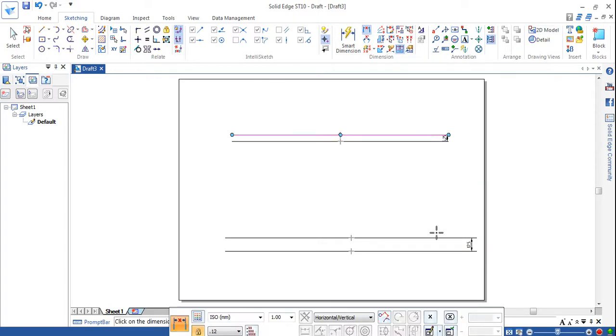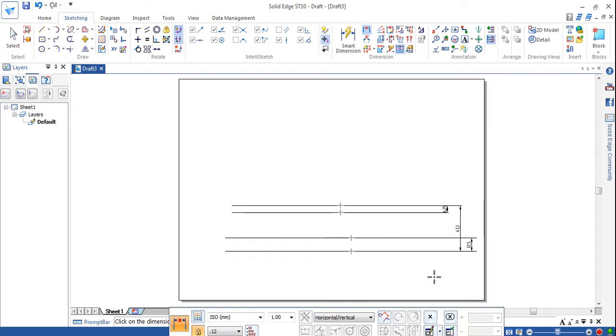Finally I'm gonna give the bottommost and the topmost line distance between them. So this should be pitch multiplied by 0.866. I repeat, pitch multiplied by 0.866. My pitch here is 50, so I'm gonna multiply 50 with 0.866. Should be 43 mm. Okay.